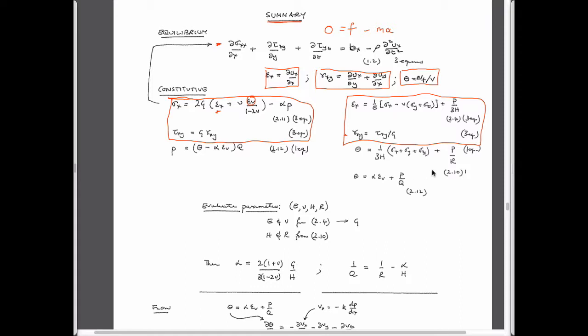And in addition to the constitutive relationships, we also have a constitutive relationship that accommodates fluid behavior. So volume strains in the fluid are a function of stresses we might apply to the system, and also fluid pressures through some coefficient. And we can get the inverse of those.